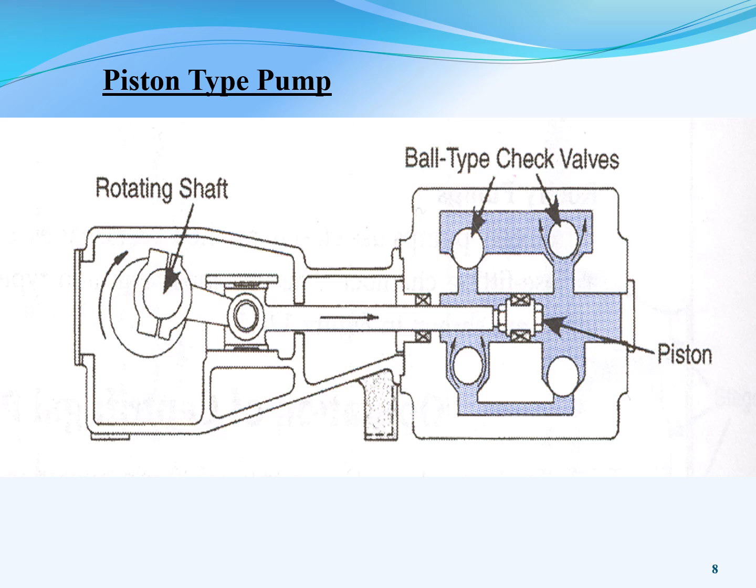Here you can see this is the piston type, and as this shaft moves back and forth, it's going to take water from either side of these check valves and pull water in, and then push that water out, right? So this is just a different type of cavity, a different kind of setup. You've got some packing glands that you can see on here, but as this shaft rotates around, it's causing this piston to go back and forth, using a calculated amount of water.